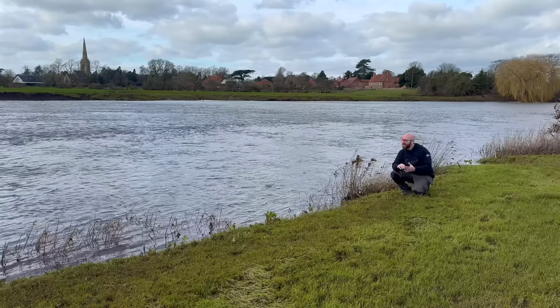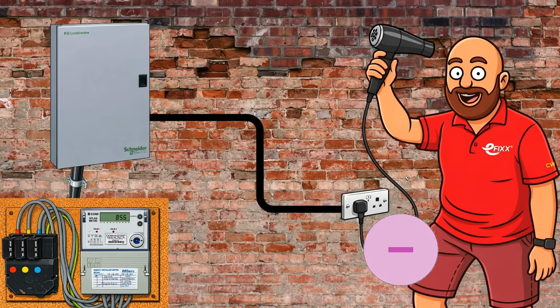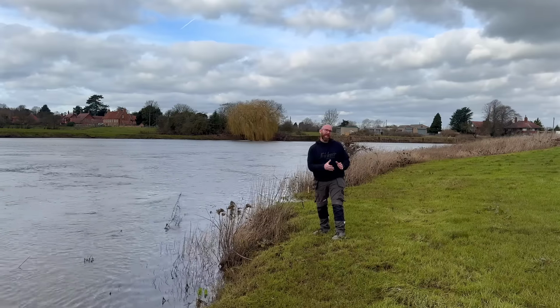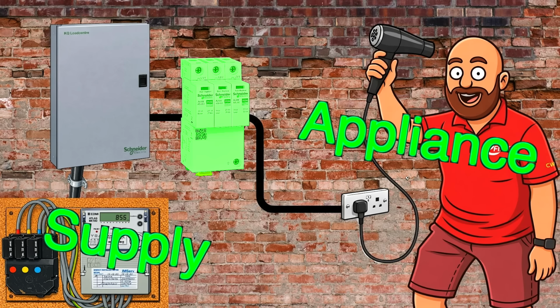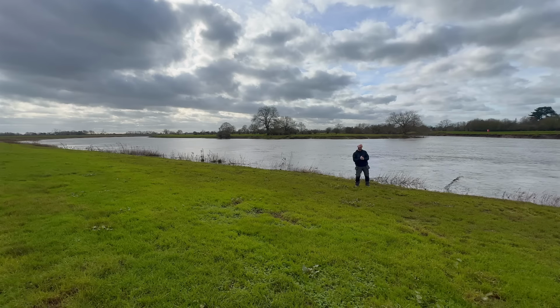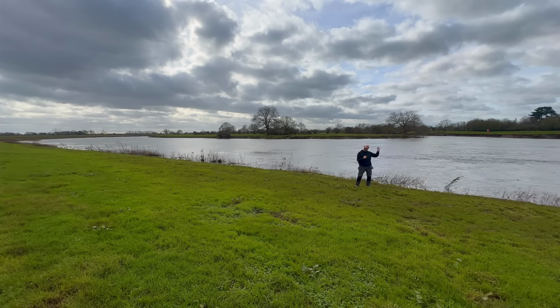Electrical current works in the same directional sense. It leaves the supply origin and flows towards the loads. So upstream means closer to the supply origin. Downstream means closer to the equipment using the electricity. If an SPD sits between the supply and an appliance, the SPD is upstream of that appliance. The appliance is downstream of the SPD. That directional relationship matters because an SPD can only control the voltage for what sits downstream of it.